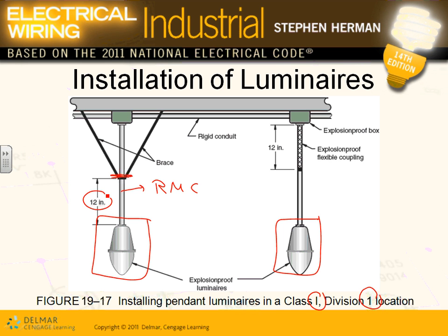If you're like Chad, hate conduits and don't like to bend them, and you want to use flexible cord or cables, no problem. You can go ahead and use it. You have to have that mesh, remember that mesh, within 12 inches to hold it, and you have to have explosion proof boxes and explosion proof couplings.